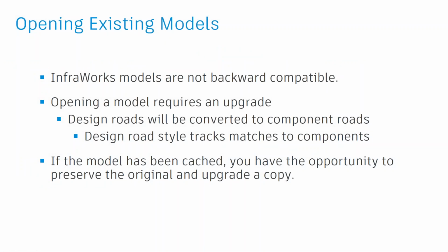So a couple of general things about opening existing models that you need to know. InfraWorks models are not backward compatible. So once you upgrade a model by opening it in the latest release, you're not going to be able to open it in an older release, and other team members aren't going to be able to open it in their older releases if they haven't upgraded. That's no different than it's been before. We realize an upgrade doesn't just affect one person. It does have a ripple effect, and others involved in the project have to be aware of the upgrade and go through it. Thankfully, the upgrade process on an individual basis is pretty simple. The way it installs is pretty quick and easy. It's just coordinating the information, so that everyone knows this project is being upgraded.